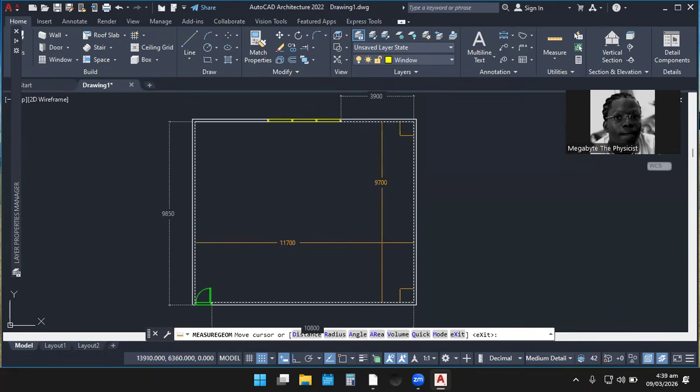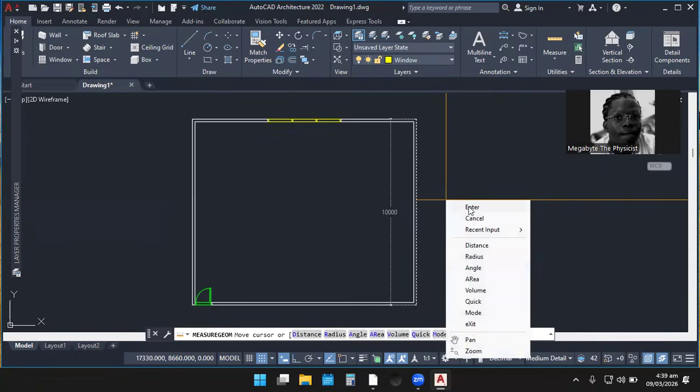So let's see if we can offset by that amount, or if we don't like that amount and we still want to maintain the same window size, what are we going to do? Let's subtract that amount from this figure and see. 9,700 minus 1,300, and you realize that we're going to get 8,400. So if that is the case, let's offset 8,400 twice. So let's remove this command.